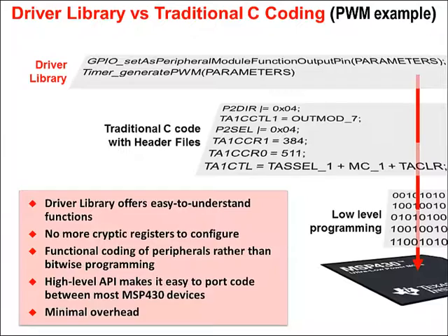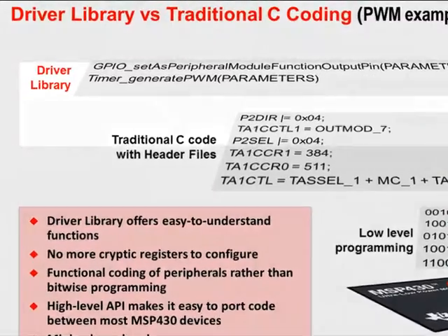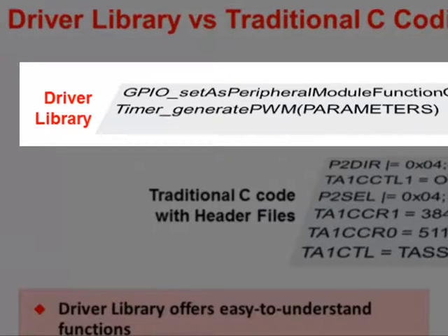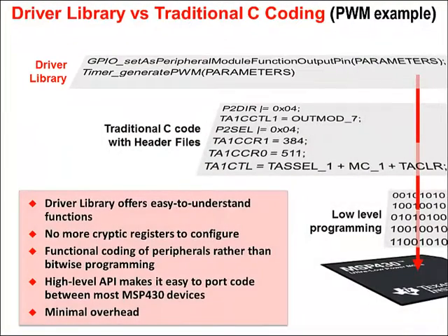Every single MSP430 device ships with a header and linker command file that define every register and every bit in every register. What you've seen from a number of TI processors, MSP430 included, in the last few years, is a driver library. This is a set of functions that allow you to control peripherals from an API. We've worked very hard to keep this API as minimal overhead as possible, so the goal of being lean and mean is very important to us.